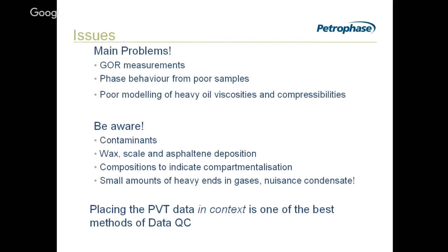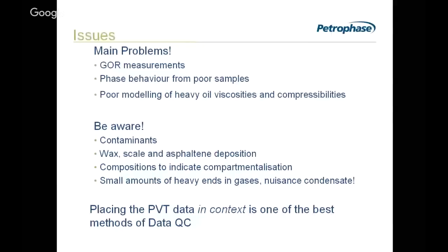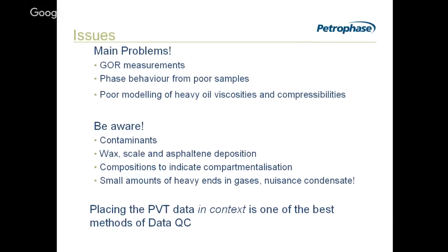So to conclude here, issues, main problems: gas-oil ratio measurements, phase behavior from poor samples. Yes, beware of modeling heavy oil viscosities and compressibilities. Be aware of contaminants. These are quite often overlooked. Wax, scale, deposition, information that's going to be needed in the development plan.